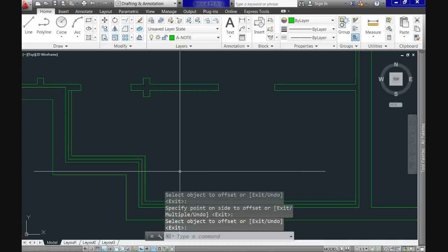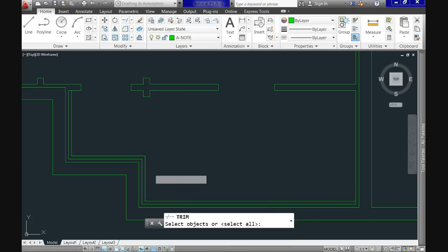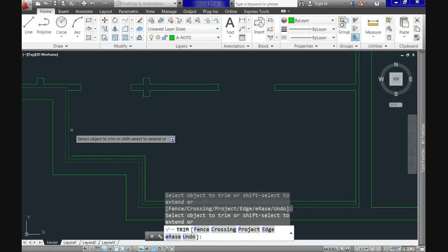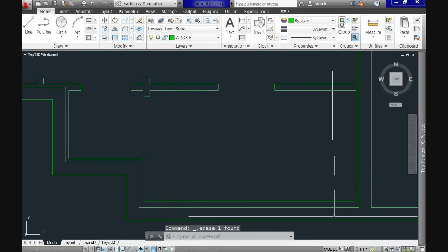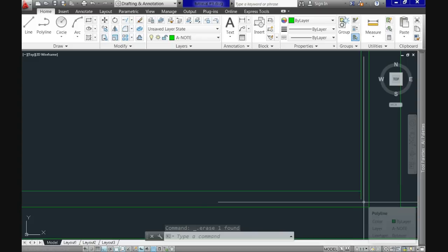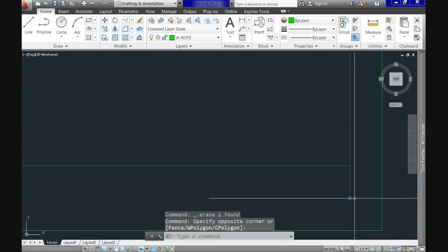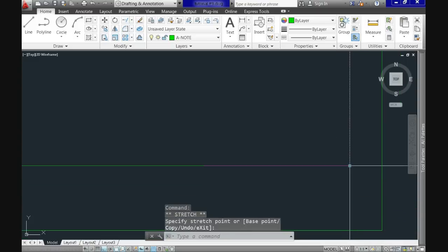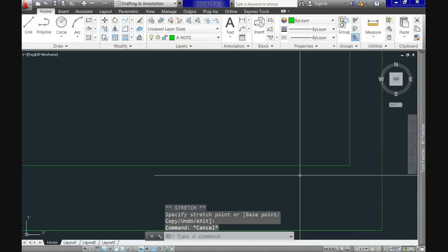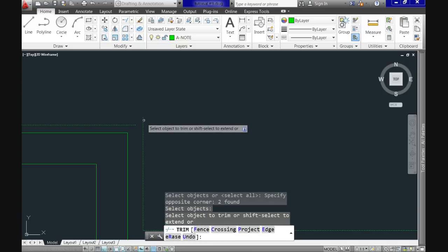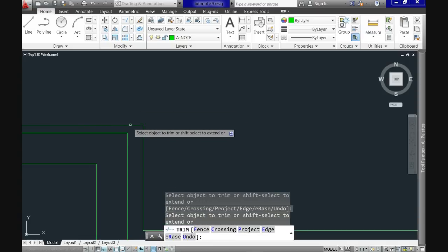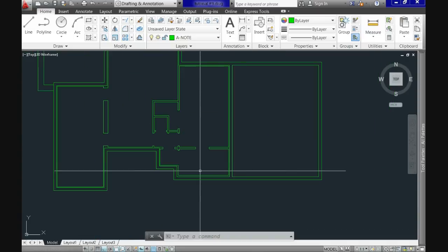Select the line. Let's trim the area to leave it as we want it. And remember that in CAD, you have several ways to do the same. In other words, you don't have to remove this line exactly the way I'm doing it, because at this point, you should also know all the ways that we've explained previously. And although we can trim again, we'll stretch the lines using the grips of the line here. Now let's use trim again. First cut this one and now extend to the other one. And yes, now we're done with our initial part for this project.